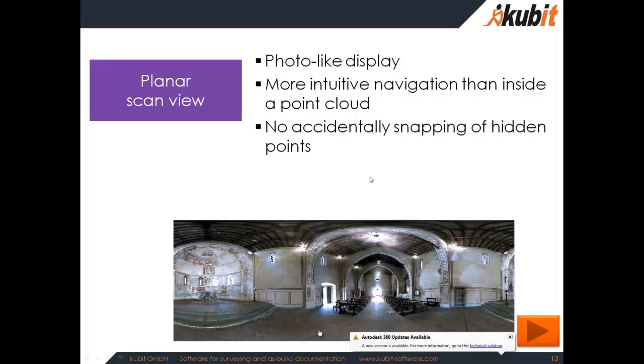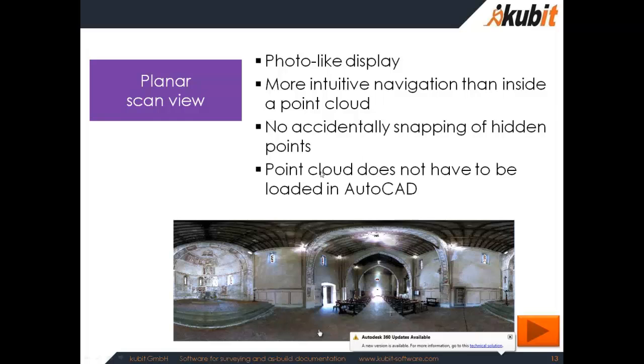You do not have the risk to accidentally snap hidden points because it's single scan based and you can only snap those points seen from that scan position, and the point cloud does not have to be loaded in AutoCAD if you use the planar view option of PointSense Heritage, which is provided with a special Vertiserve license, which is included in the PointSense Heritage package.